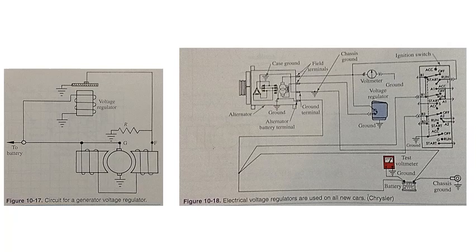In operation, these contact points vibrate. They alternately cut resistance in and out of the field circuit and maintain a constant voltage output of the generator. Mechanical magnetic relays have served this purpose for many years. Now, however, electronic devices are being used on cars. An electronic regulator using an integrated circuit for the switching function is shown in figure 10-18. A study of integrated circuits is found in chapter 19 of this text.